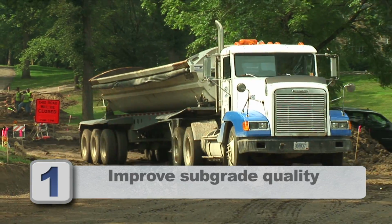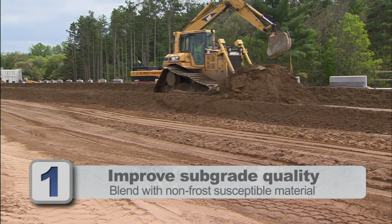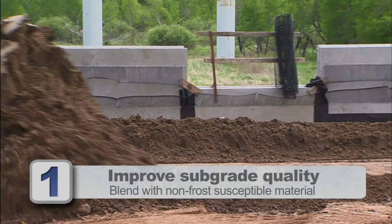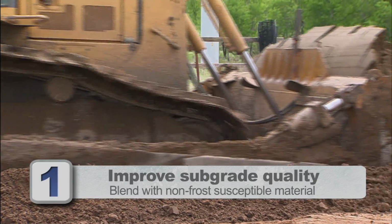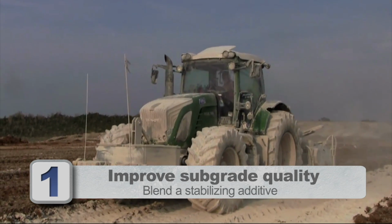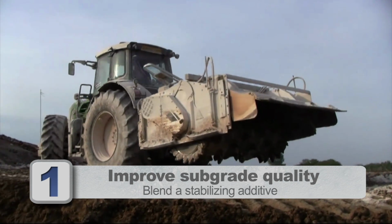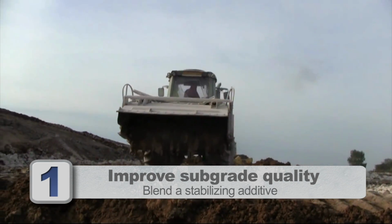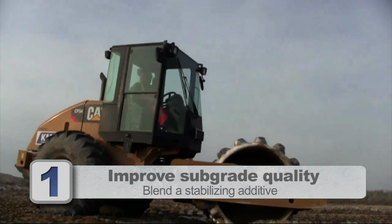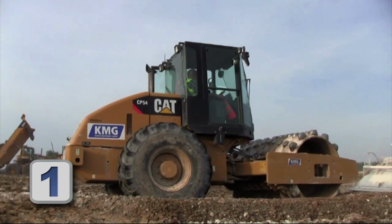A less expensive approach is to blend non-frost-susceptible material into existing frost-susceptible subgrade soil. This method reduces the occurrence of differential frost heave in the pavement by achieving greater consistency throughout the subgrade. A more expensive alternative is to blend a stabilizing additive such as fly ash, Portland cement, or a proprietary product into the existing frost-susceptible soil. These materials either harden the soil or prevent excess moisture accumulation so the soil resists frost action.